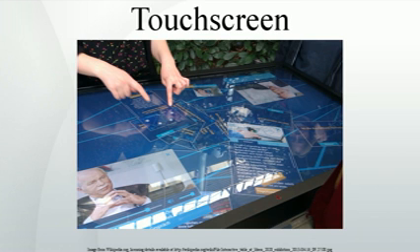Ergonomics and usage. Fingerprints. Touchscreens can suffer from the problem of fingerprints on the display. This can be mitigated by the use of materials with optical coatings designed to reduce the visible effects of fingerprint oils, or oleophobic coatings as used in the iPhone 3GS, which lessen the actual amount of oil residue, or by installing a matte finish anti-glare screen protector, which creates a slightly roughened surface that does not easily retain smudges, or by reducing skin contact by using a fingernail or stylus.